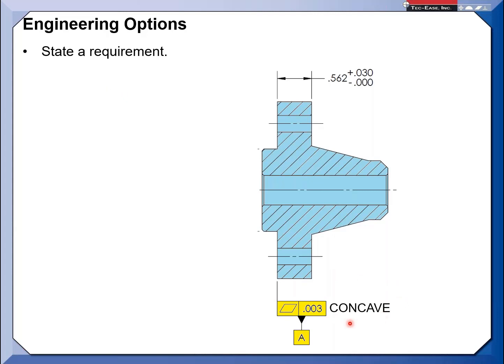So the standard does allow for line elements, radial elements. This is just another requirement saying that in this case, the tolerance zone is still the same, 2 parallel planes, but all of it goes into the material. Now, yeah, you can get contact in the fringes. This becomes a stable, repeatable datum reference frame. It's not a rocker, but it may still leak if this was a fluid type application. So I was just addressing some of the comments that I've seen people submit, that these are things engineering would have to consider. How do they handle that?